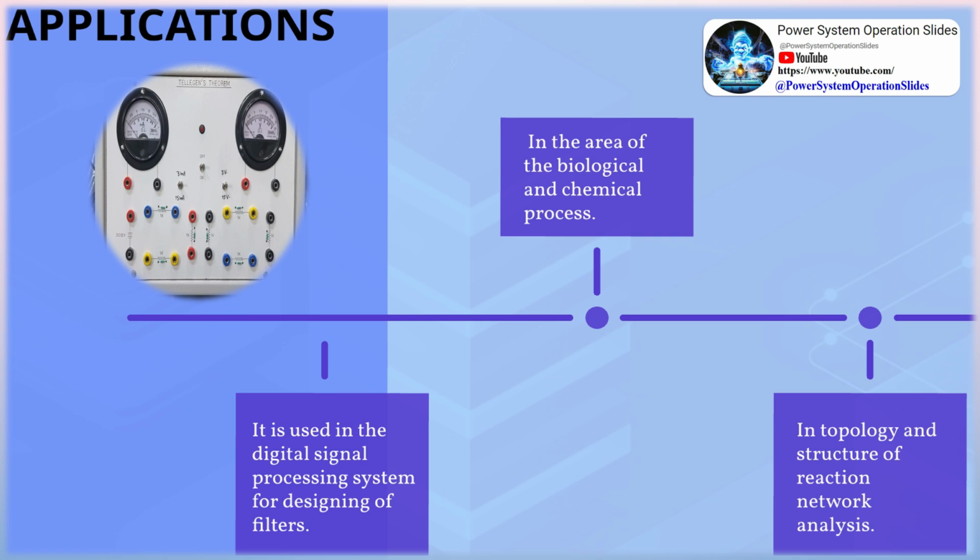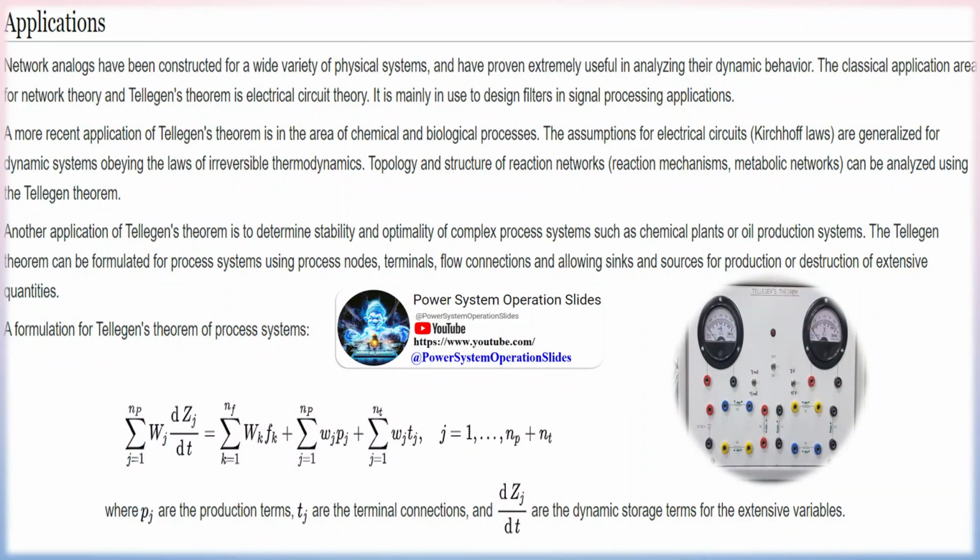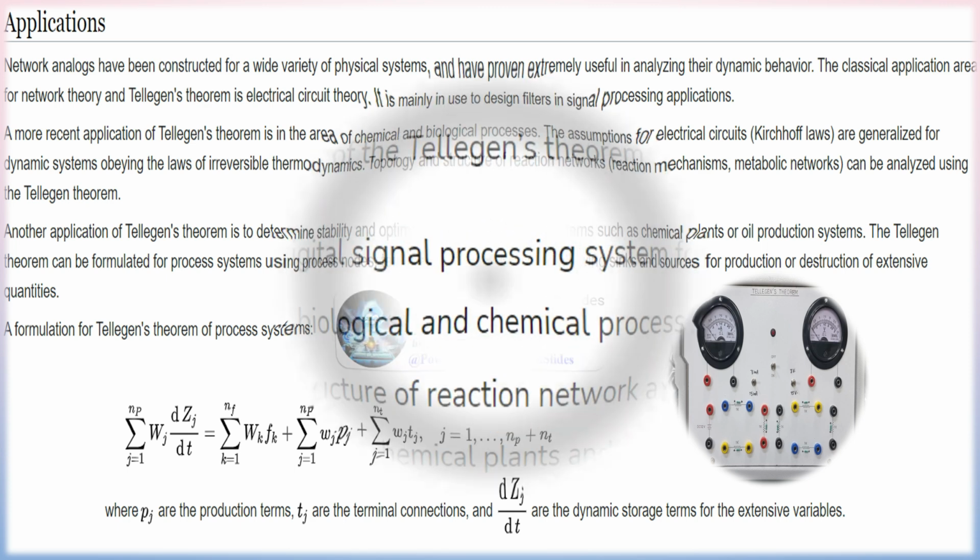The theorem thus applies to all electrical networks that obey Kirchhoff's laws, whether linear or nonlinear, time invariant or time variant, reciprocal or non-reciprocal, passive or active, single-valued or multiple-valued, hysteretic or non-hysteretic. The excitation is arbitrary. It may be sinusoidal, exponential, periodic, transient, or random. Also, the initial conditions may be arbitrarily chosen. The modern interest in nonlinear and time-variant networks gives Tellegen's theorem a special new importance, because it is one of the very few general theorems that apply to such networks.